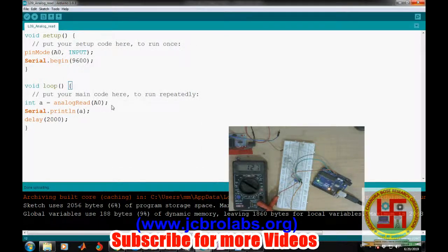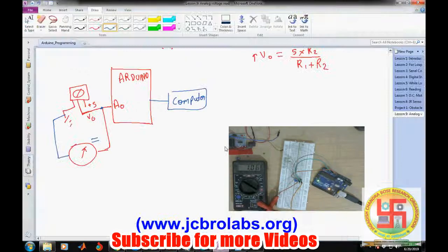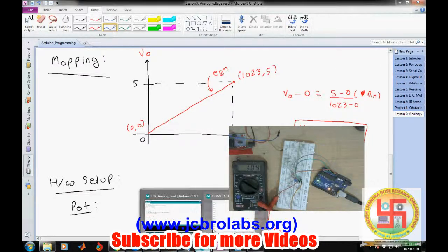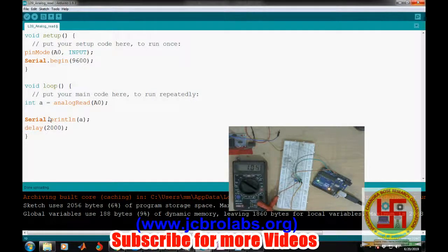So let's do the mapping, or let's implement this particular formula which we derived here, right? So okay, int b equals to this, multiplied with 5.0 because this value will be in float. If we simply write 5 and 1023, the result will be integer only. So we have to keep that in mind. So print and then Serial.